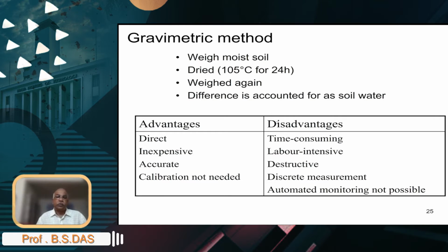But the whole purpose is that you need to remove whatever free water is present, and whatever method you choose, it has to be a laboratory based method. So you have to have some kind of drying equipment, and as of today, the gravimetric method still is the standard method against which all remaining indirect methods are being compared.